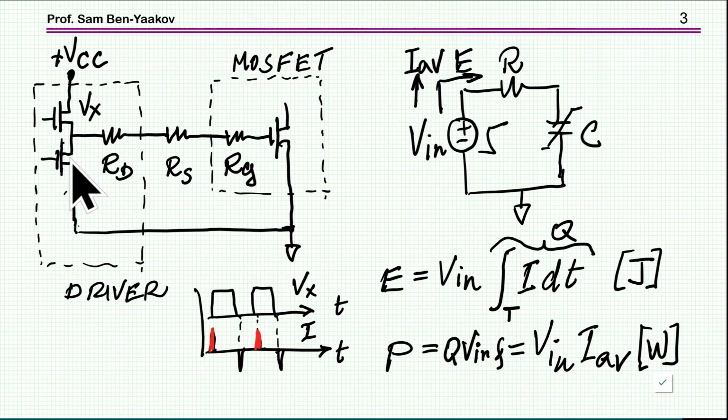And it could be like two N channel, but then you need a high side drive, so many times it will be an N channel and a P channel. This will be a simplified approach. And then there is a resistance. I'm showing here one resistance for the two MOSFETs. In some cases it will be different resistances for the high side and low side.